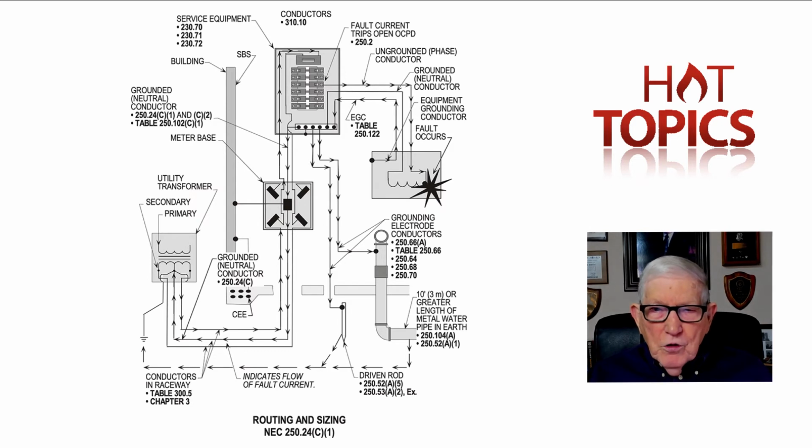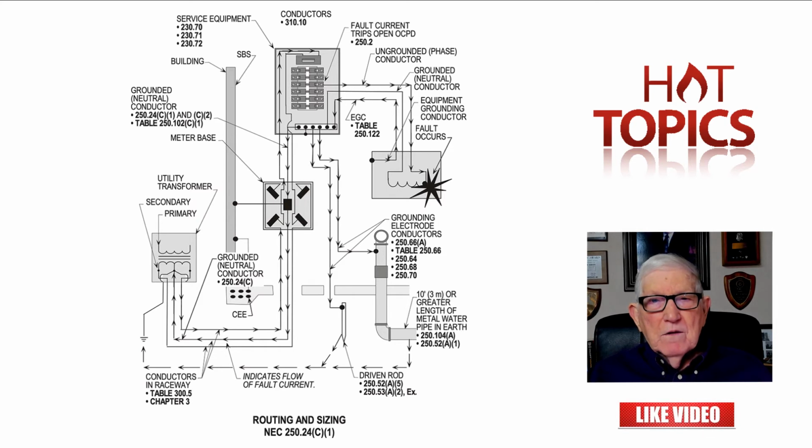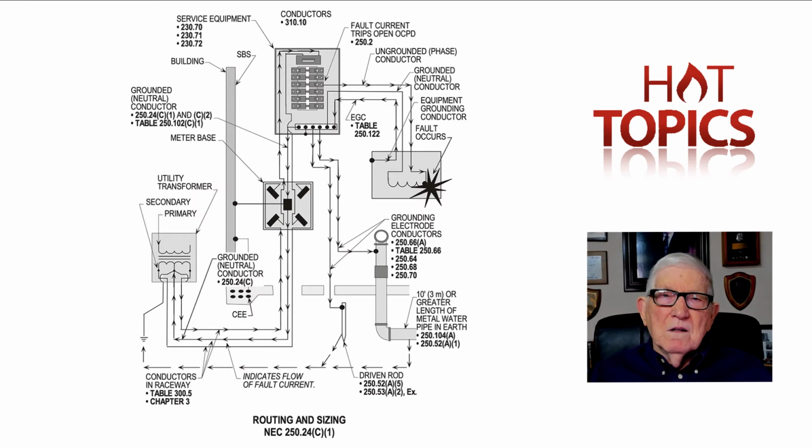And then notice, if you're an equipment ground, you're in parallel. You're connected to earth ground here, but you're connected to the metal here, where the neutral is prohibited from being connected when you look at 250.6 and go through that series of where the neutral cannot be connected to metal on the load side of the service. It's just where it's earth grounded. So that's why it's a short circuit from an ungrounded conductor to an ungrounded conductor, or from an ungrounded conductor, hot conductor, sometimes you call it, to the neutral. But a ground fault is when it's the ungrounded conductor, hot conductor, to metal. That is considered a ground fault.